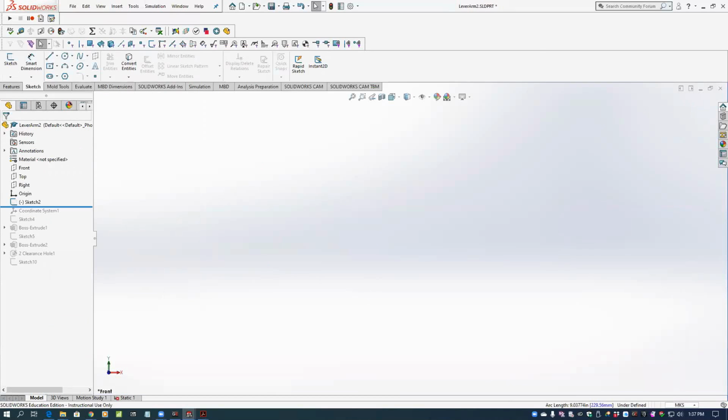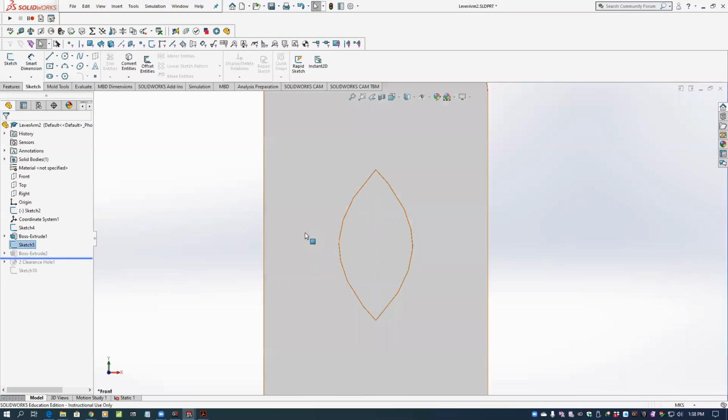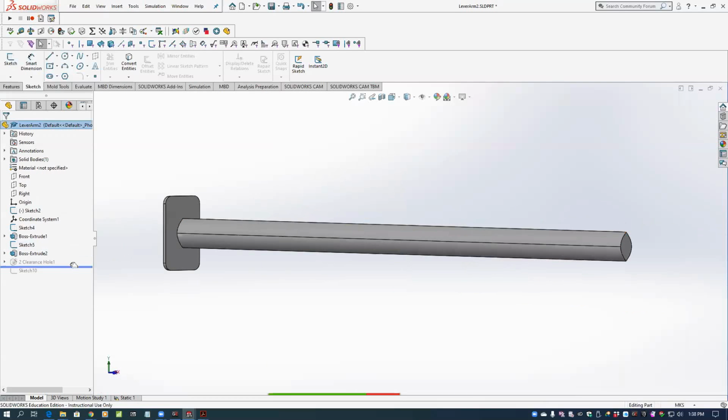I've changed it to meters here for the rest of the beam, but then I use that profile to create the complete cross-section here, mirroring those profiles about the y-axis, and then those two about the x-axis to create the profile, and then extruding that and adding a plate on the end just for visualization and appearance purposes.